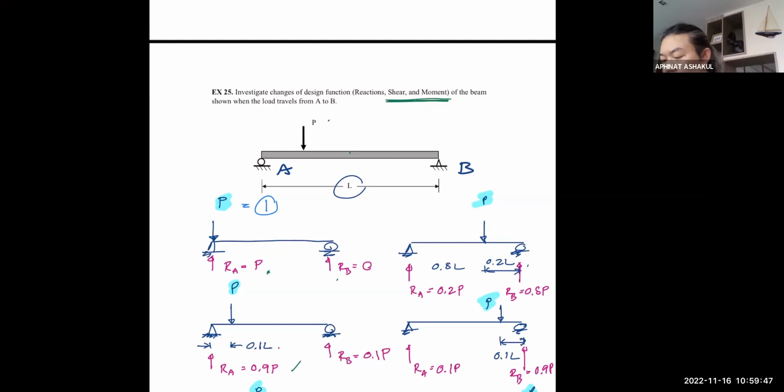So now focus and clear your mind and trust your force. We are going to place the load at each location like before. But in order for us to have the shear and moment at these locations, we now have to do a little old school business called cutting the free body diagram.